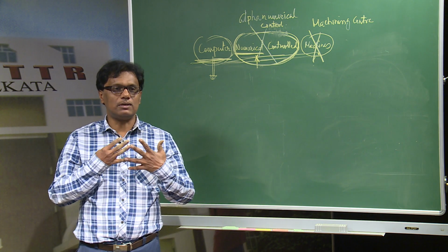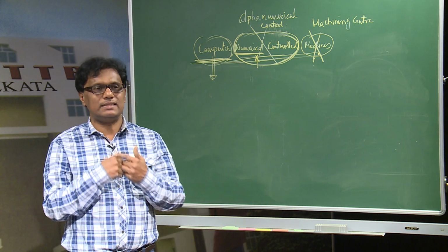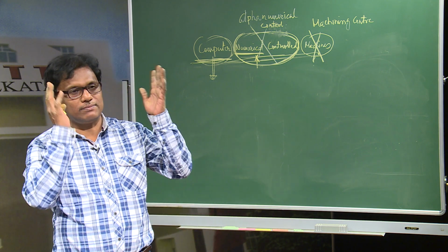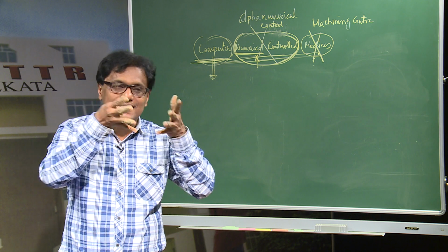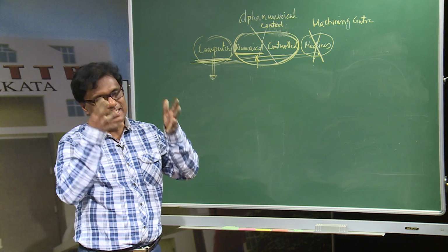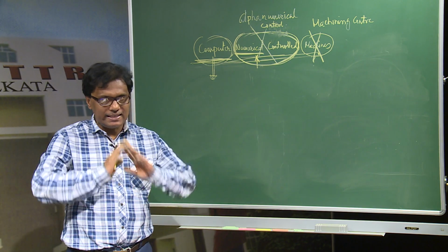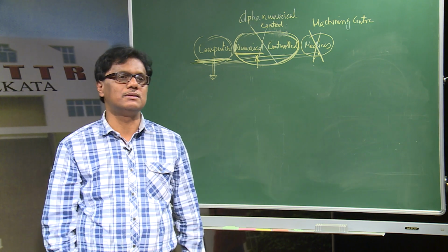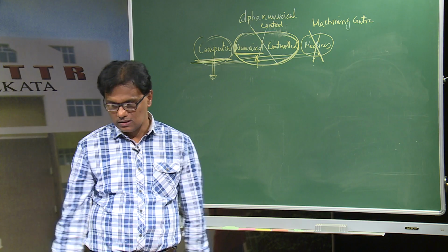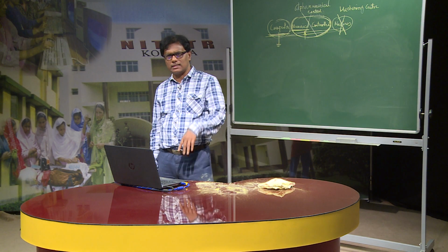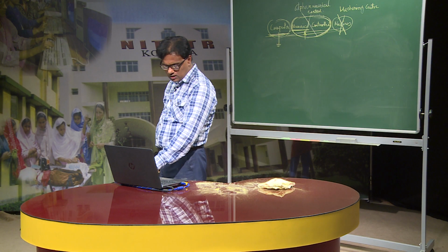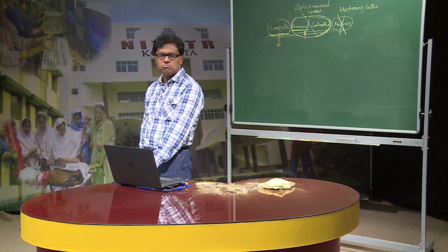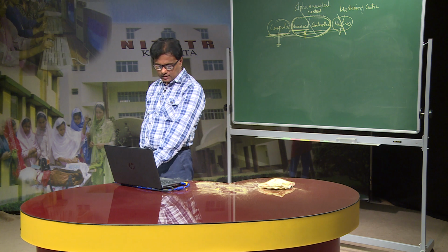Actually you can't build or design a CNC machine arbitrarily. There is some standard, that means which axis will be the x axis, which axis will be the z axis. In fact, in any CNC machine, the job axis is the z axis. So, these are some of the standards, such as the typical type of lead screw available.